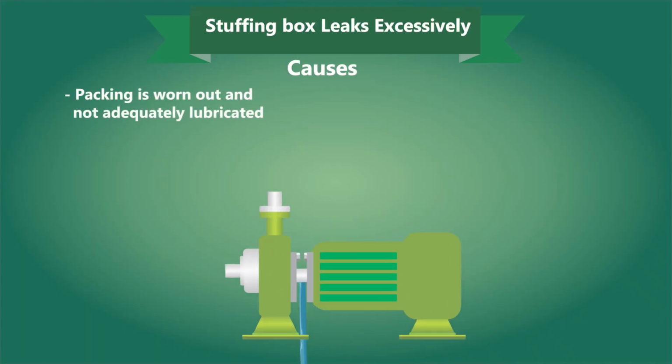Now if the stuffing box leaks excessively, then it might be because the packing is worn out and not adequately lubricated, and it is also possible that the shaft has bent.